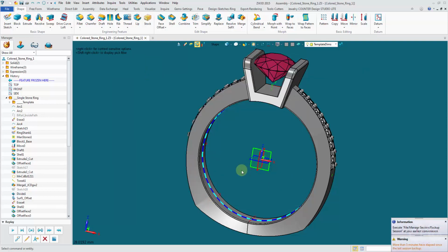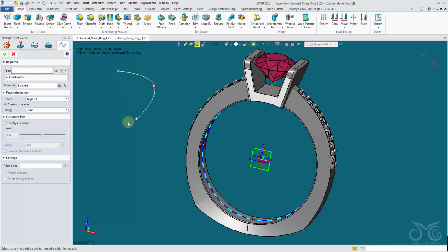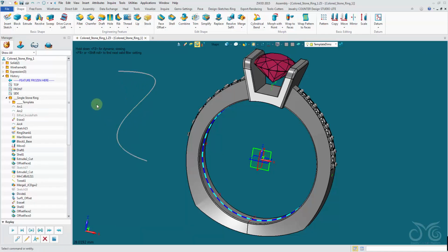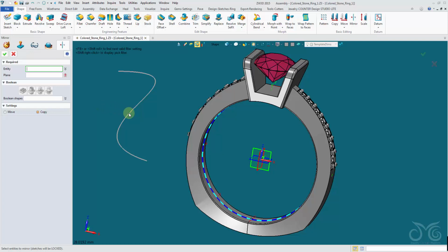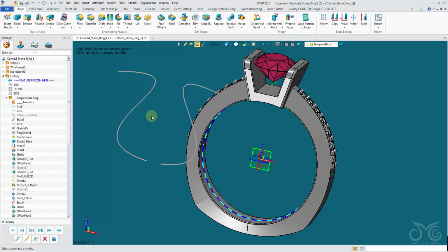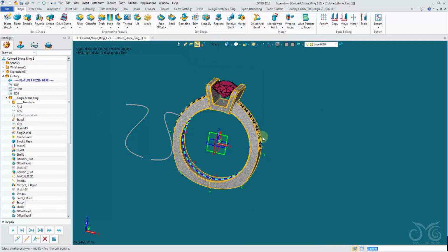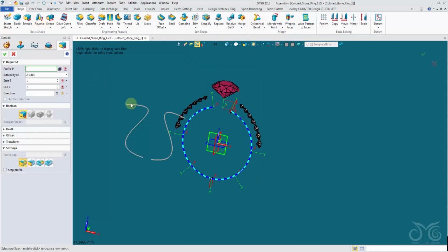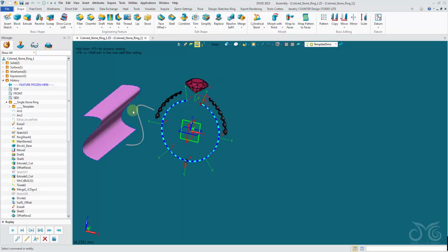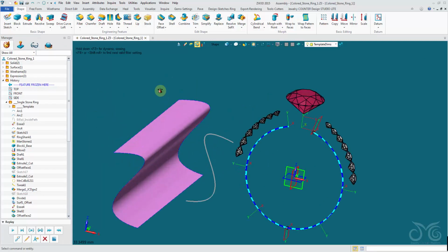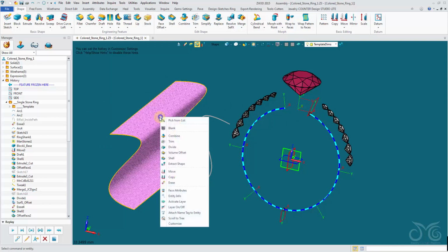Okay, so these are just adding a few hotkeys that can help speed up our designing. Curve, by pressing C, we get the 3-point curve. M to mirror. Okay, B to blank. E to extrude. Okay, so these are some of the hotkeys. Okay, also remember that we can get quick access to some commands with our right-click options.